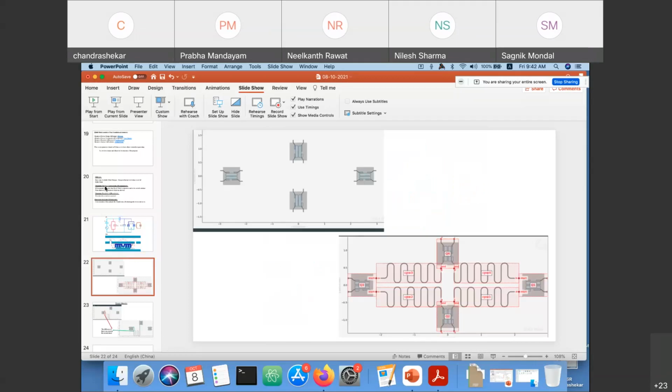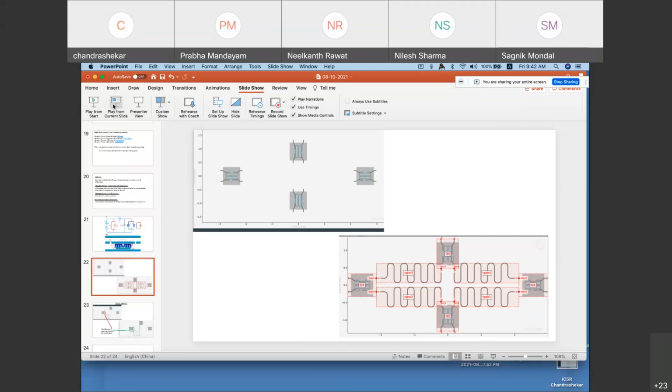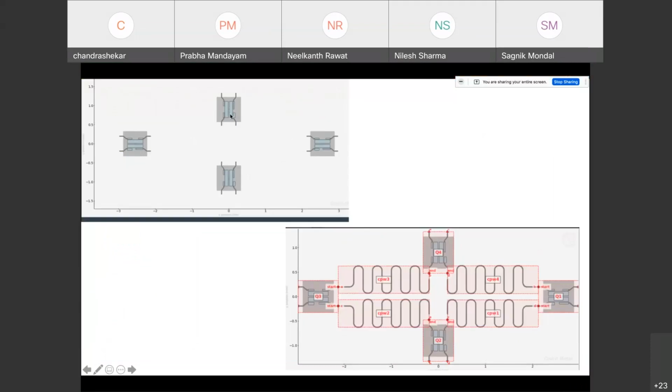So using this Qiskit Metal, what we can do is we can write down 4 transmons. We can draw these 4 transmons. Actually, even within this transmon, you can individually draw each one of these blocks. You can actually set the spacing here, and you can see this one is a connector wire and there is a read wire, and you can actually design each one of them.